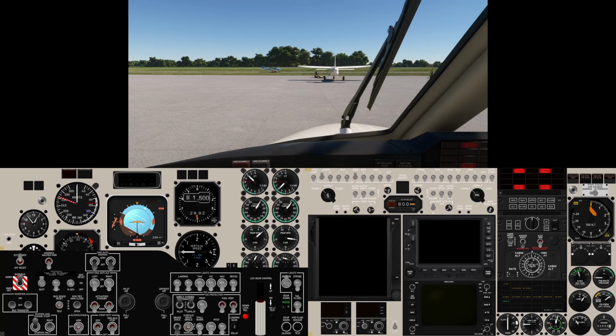Luckily, I think I turned the failures off before I started this. But yeah, something you have to be careful of. You do need a separate condition lever mapped, and I didn't have one here when I set up for this, so I only had the one, so I'd already put it in. The way around that, of course, if you can't get over that, is you have to sort of cheat a little bit and start both engines at the same time, which you would never normally do. Too much drain on the electrical system. But because the fuel was already in, that's why we got a hot start. So you can see that's modelled in the aircraft.